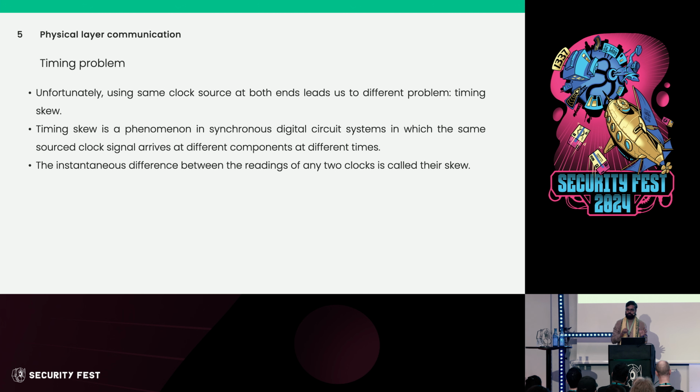What is the purpose of those squiggly lines on the PCB? Or why are we taking a much longer route than optimally needed on the PCB? Ever thought about it? Do you know the answer? Delay. Sorry? Delay. Yes, you want to set both wires of the signal at the same length.